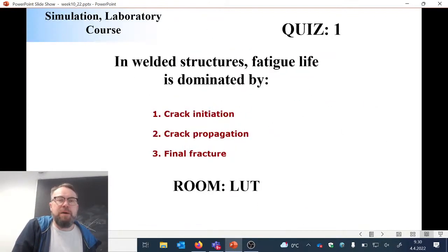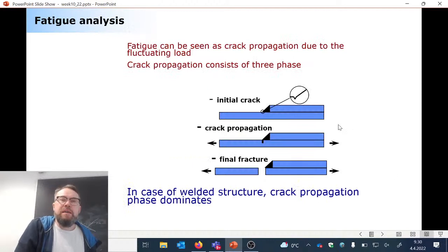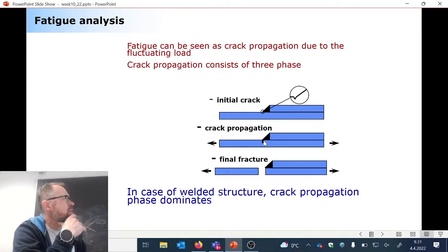So let me take myself back here. What you can do is use maybe TIG welding to try to get rid of these initial cracks. This is one way you can do it. Or you can hammer this welded toe, try to get these initial cracks away.